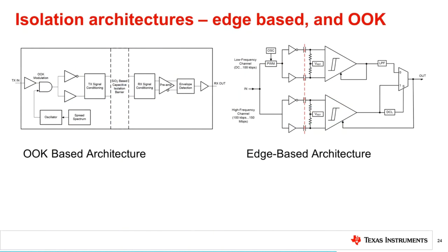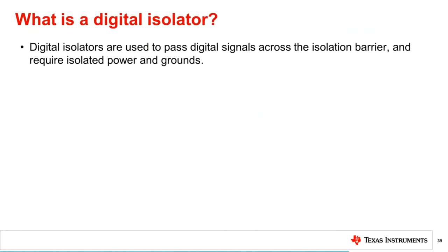So which capacitive digital isolator topology is really the best for your design? In addition to the critical isolation specifications, when considering each architecture, just remember to consider the additional design priorities of power versus data rate, highest possible common mode immunity, and managing for error conditions to help determine the best fit for you. This completes our introduction to digital isolators.